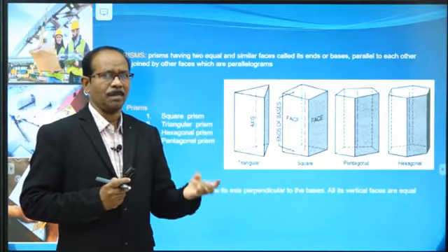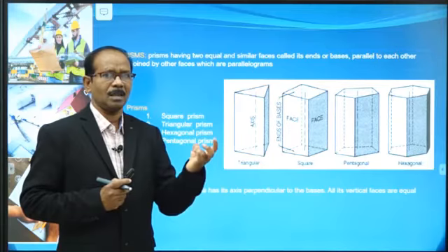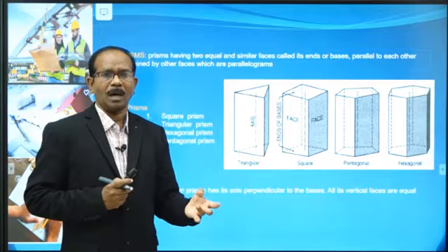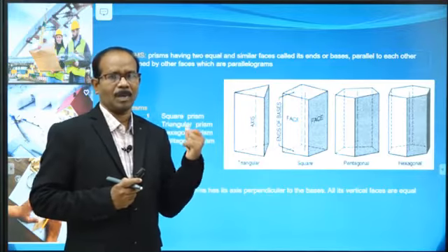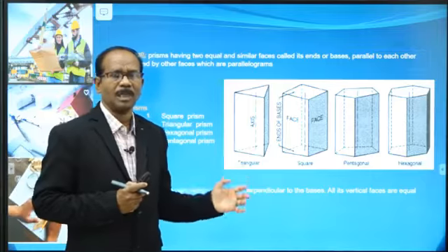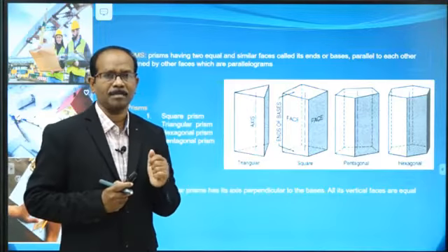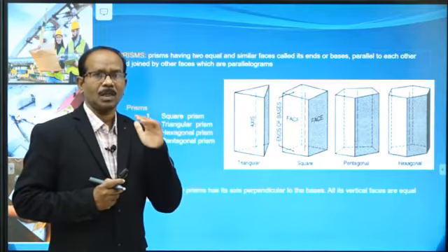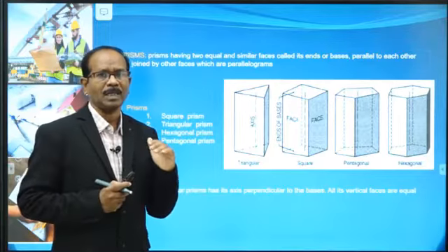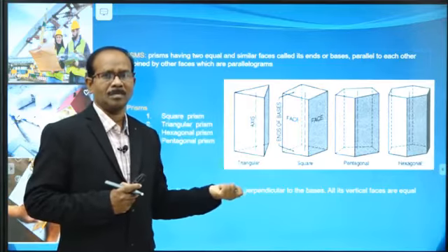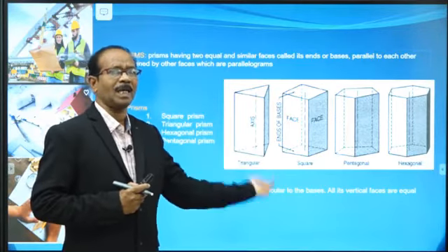Thick line is used to highlight the result of an object. Thin line: initially start drawing any object with thin line. Then any invisible edges need to be represented with dotted line. Axis of a prism is represented with chain line.